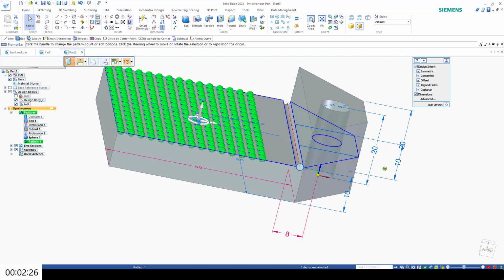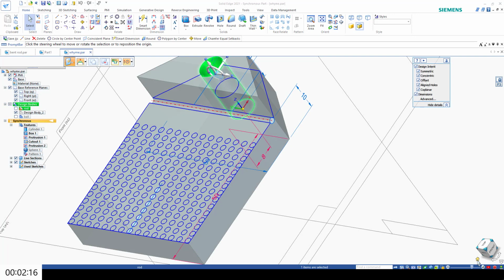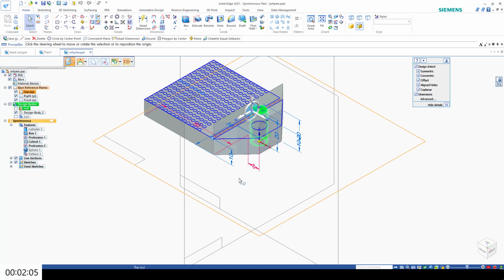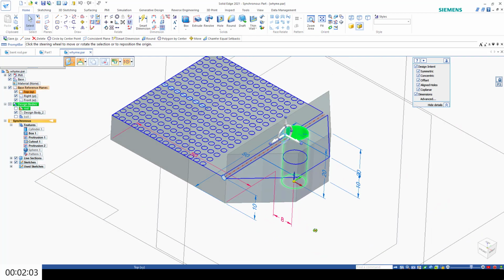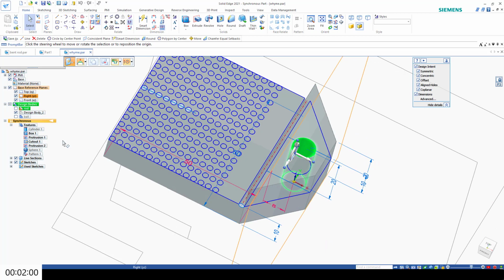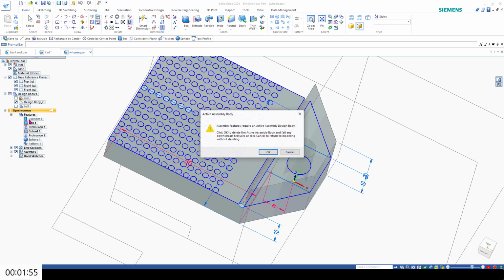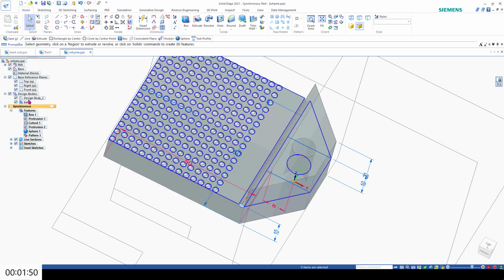There's all the spheres. We have about 2 minutes left, and I'm going to quickly put the design body and the balls together. Now, I realized well after the fact that I wanted to apply a thin wall condition to this object, and it would not work. What I realized is I should have applied a thin wall to the design body too before I merged the design body and the balls. I'm also deleting the rod feature because I'm not going to need it when I'm 3D printing, and it's just going to get in the way.